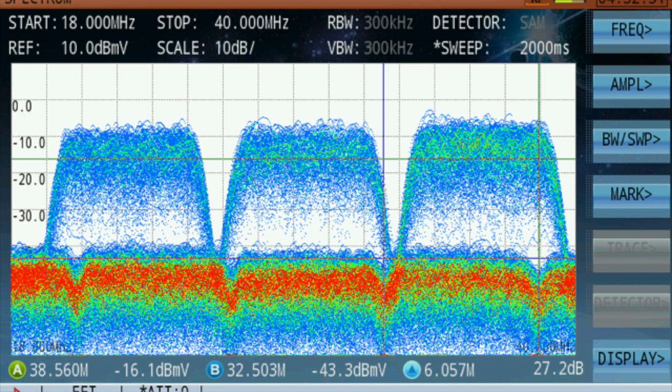Because of the high analyzer sensitivity, the DPS picture is able to show a more detailed digital signature of the reflected downstream signal, down to about -63 dBmV, as opposed to viewing through a signal level meter device, which would simply show a slightly elevated but flat noise floor.